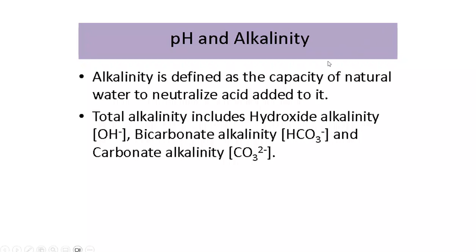Then next we have alkalinity and pH. Alkalinity is defined as the capacity of natural water to neutralize acid added to it. Total alkalinity includes hydroxide alkalinity (OH), bicarbonate alkalinity (HCO3), and carbonate alkalinity (CO3).